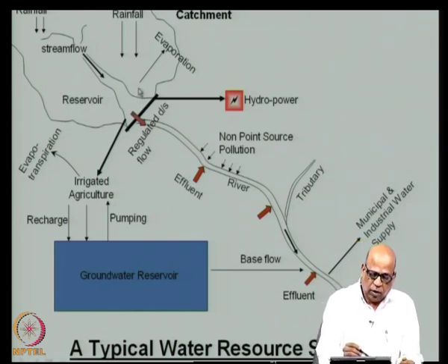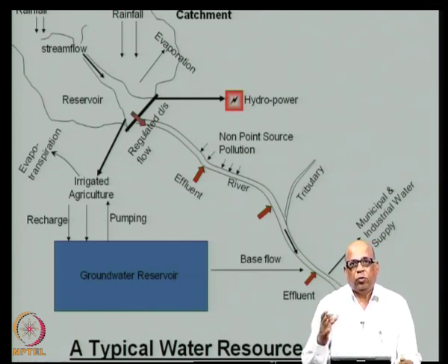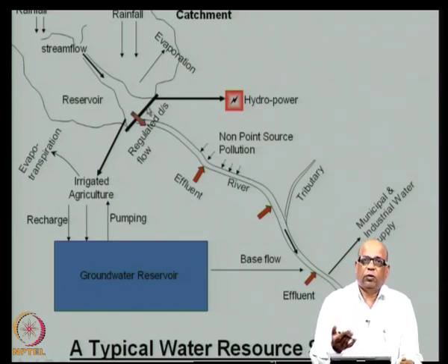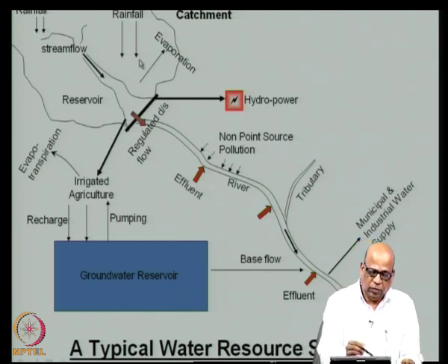So, you need to account for evaporation, and then from the stream flow you also have infiltration that is taking place, seepage that is taking place. So, these are the losses from the storage. You built a storage reservoir to essentially store the water for use for different purposes. As you created the storage, there will be losses because of infiltration that goes below the ground, and losses because of evaporation, as water evaporates into the atmosphere. So, we have to account for these losses.